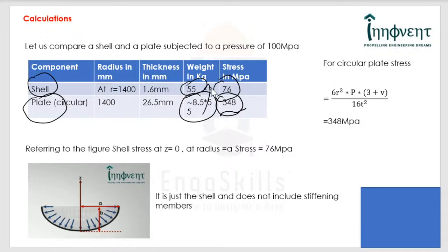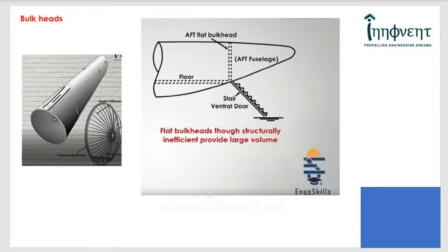Of course, it is highly idealized, but this would have inspired the interviewer. And why? Because in aircraft, bulkheads are used where large pressures have to be reacted. Of course, there are exceptions where you require space.